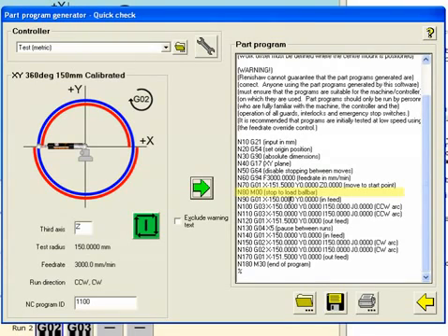Once we hit cycle start, the first feed moves into the measurement range of the Ballbar. We continue counterclockwise through a G03 move. The first 180 degrees of that is thrown out to make sure that we're up to full constant velocity. We continue 360 degrees of data capture, and the last 180 degrees is thrown out as well. The last move is the feed out, which stops the data capture of the counterclockwise direction move.